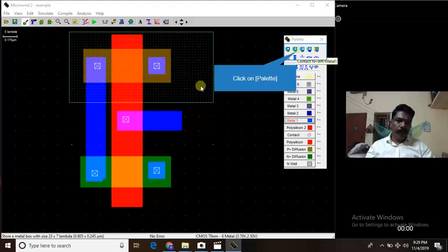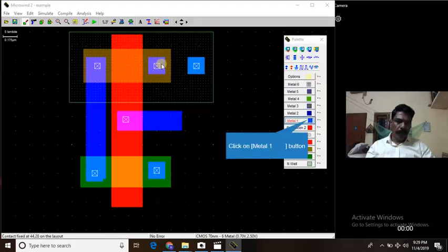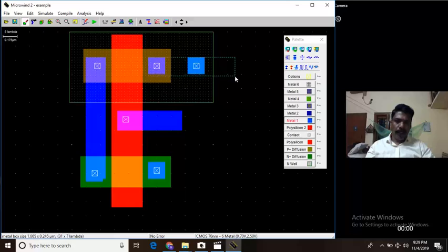To take a contact from the N well, what you have to do is make an N plus diffusion into that and take contact. So put an N plus diffusion on N well, with an N plus to metal contact. Something like this. Now you connect both of them, both are top metals, and take like this.